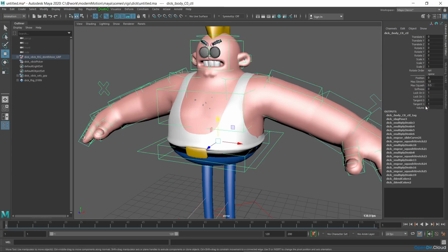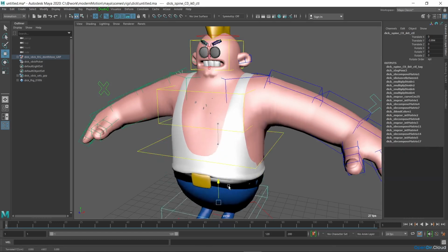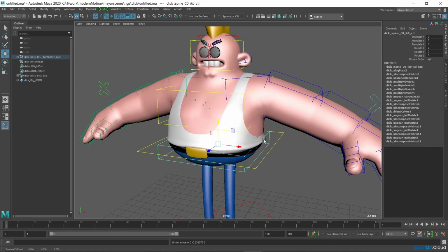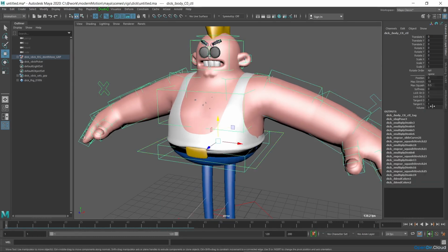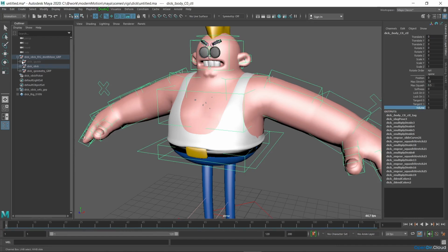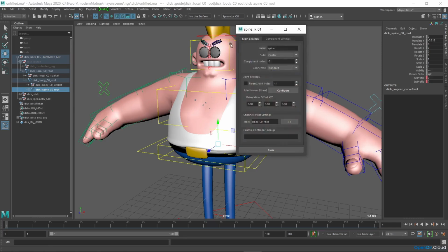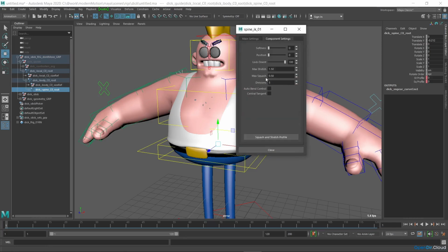The volume attribute controls the effect of volume preservation during stretching and squashing. If it's equal to 1, the spine will become thinner during stretching, and thicker during squashing. Decreasing this parameter reduces the effect. Now the spine is short and the effect isn't very visible. The value of squash and stretch is set in the component's guides before building the rig. With the help of these curves,